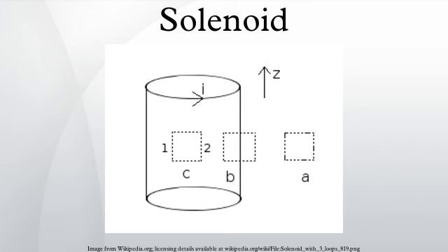Outside, a similar argument can be applied to the loop to conclude that the field outside the solenoid is radially uniform or constant. This last result, which holds strictly true only near the center of the solenoid where the field lines are parallel to its length, is important inasmuch as it shows that the flux density outside is practically zero since the radii of the field outside the solenoid will tend to infinity.